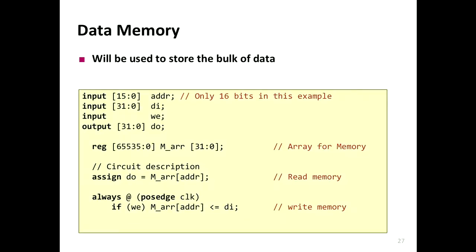And in Verilog, you would implement something like this. So you have 65,536 values. How do you read this? Exactly like the register file, remember. So you have 32-bit values and 65,536 of them. So it's an array, and your data out is a simple access to the corresponding address, which here is just 16 bits, but we will come to why later.